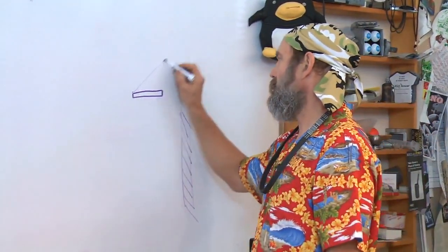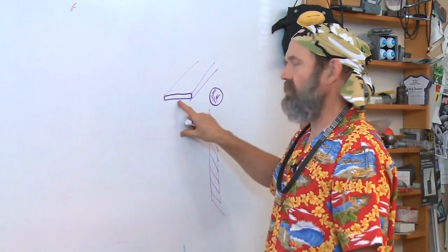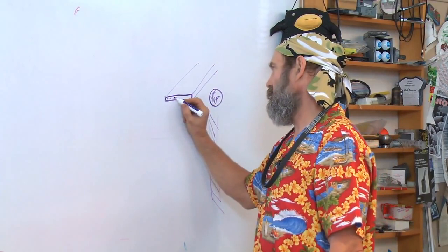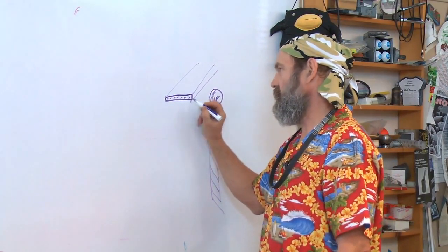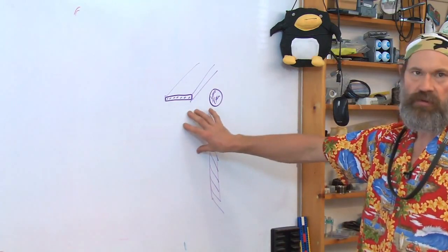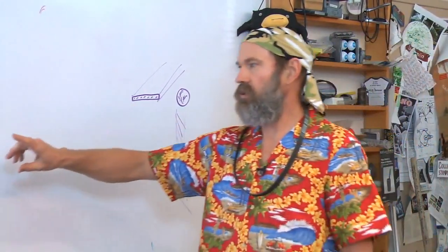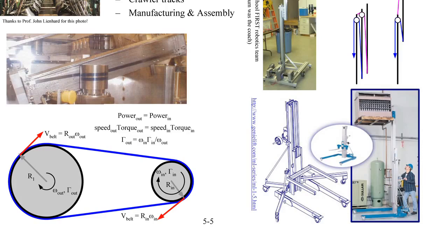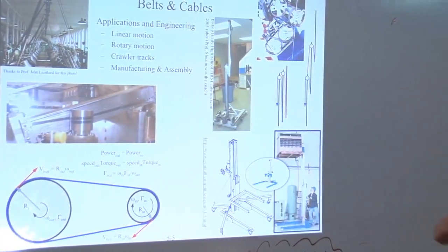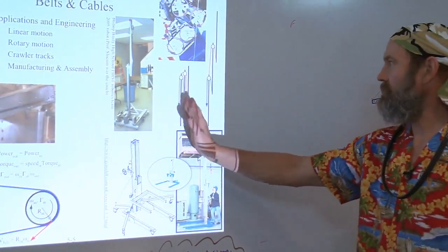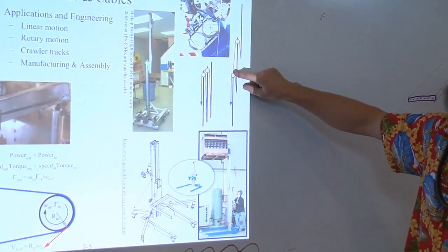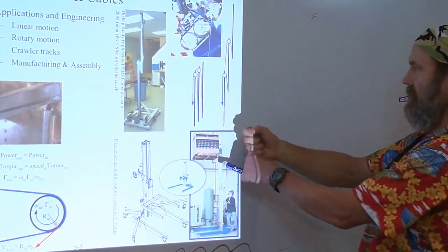A belt, maybe something as simple as a leather belt. Leather is very, very strong. Or a rubber belt with reinforcement strands, Kevlar or steel on the inside. Both amazingly wonderful power transmission elements. Works with pulleys and sheaves. Remember the capstan effect? That's what allows you to transmit torque. You can have multiple stacks of mechanism with sheaves. So you can have extending mechanisms.